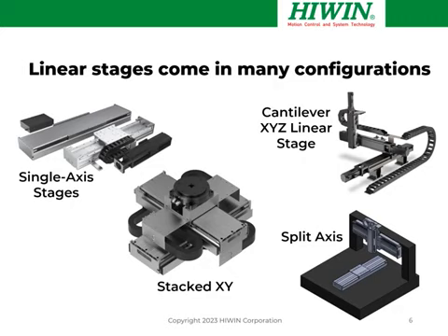Another type of design that's common is the split axis design. This design is space saving and offers some potentially higher accuracy because you can decouple the axes from each other. However, it requires a structure to support it. Another configuration is the cantilevered XY or XYZ. In this type of design, the workpiece is usually stationary and the process tool moves above it. It's a lower cost system approach, but it does have some limitations for longer travels.